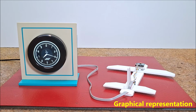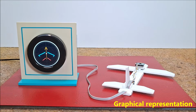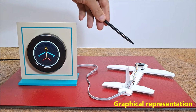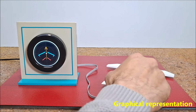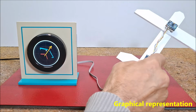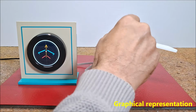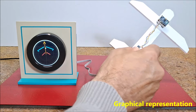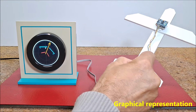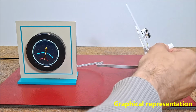A fourth display mode was implemented to provide a direct graphical representation of the MPU6050 measurements. This screen displays a simplified aircraft model that rotates according to the measured roll angle and moves vertically according to the pitch angle. This visualization serves both as a demonstration and as a diagnostic tool, allowing easy verification of sensor operation and aircraft orientation in real time.